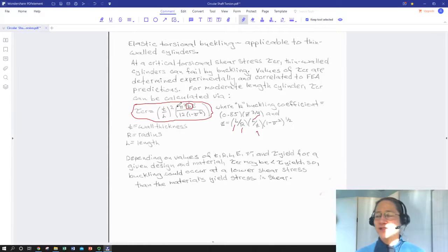So now you can see the shaft geometry is involved at many points in this expression through both K and our prefix expression. And then again we have the Poisson's ratio showing up. So we could probably ditch a lot of this other stuff and just write things simply in terms of L, R, T, Poisson's ratio, and our elastic modulus.